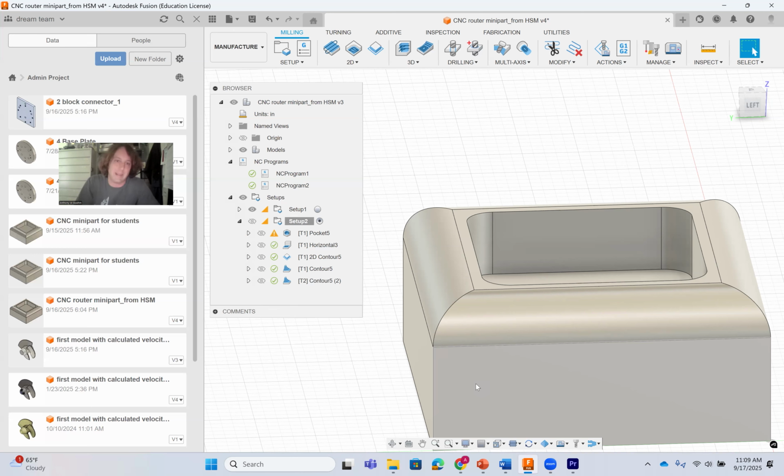We use tape primarily, and you can tape things down. It works pretty well most of the time. Sometimes with aluminum, you'll opt to have additional screws in the material, and you might even make it so that the part is tabbed, or has connecting pieces to your bulk material. I'll talk a little bit about that later in the video.